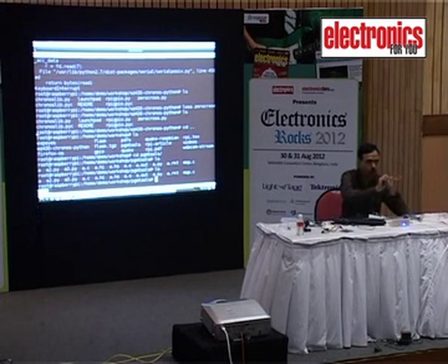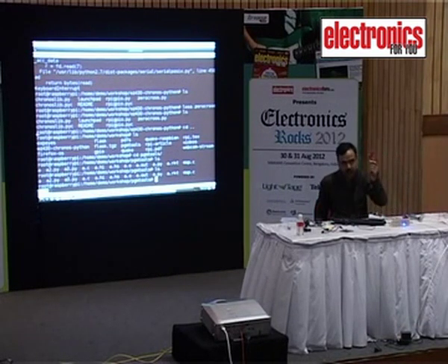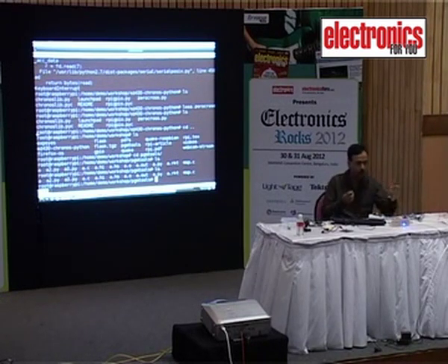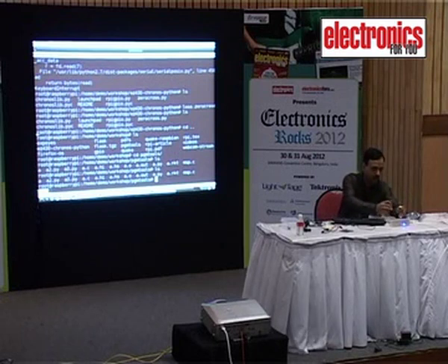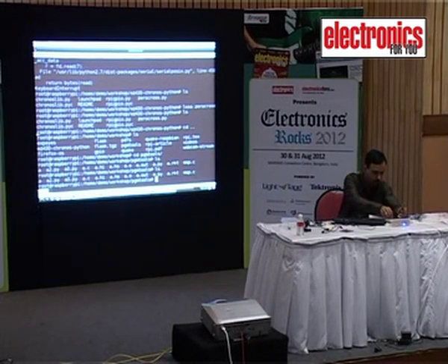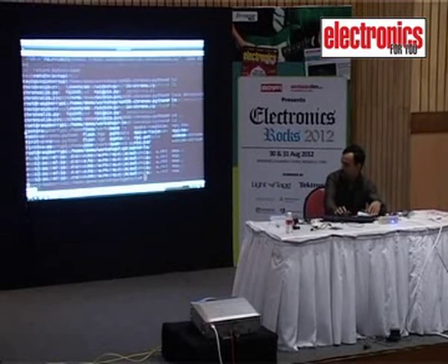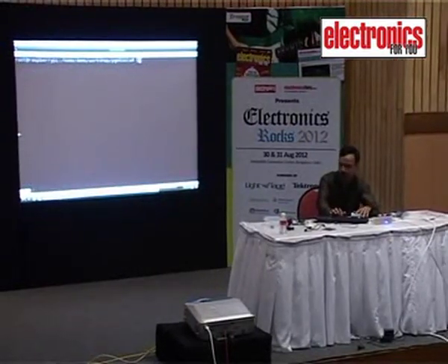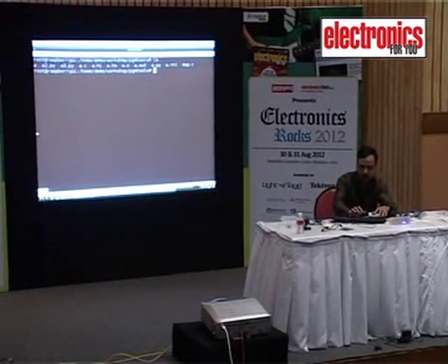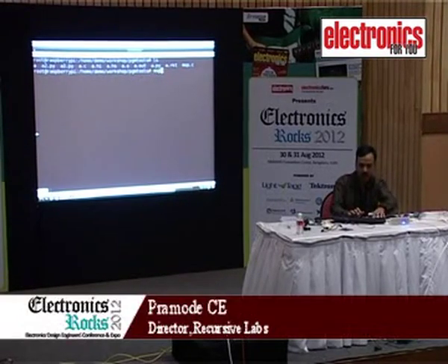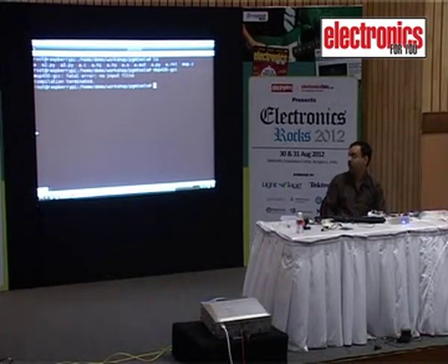I have a small microcontroller here. This is the TI MSP430 Launchpad. It's quite easy to program it using the Raspberry Pi, somewhat similar to your Arduino. Just plug it in to the USB port. If you want to write code for the MSP430, you need to have the compiler MSP430 GCC installed. That's available.